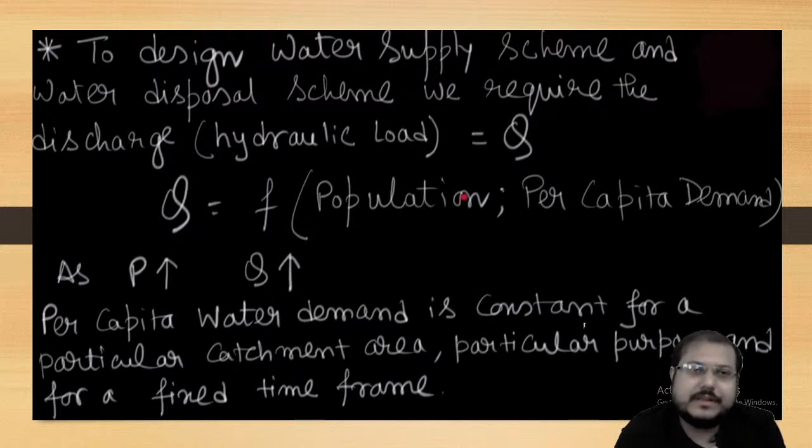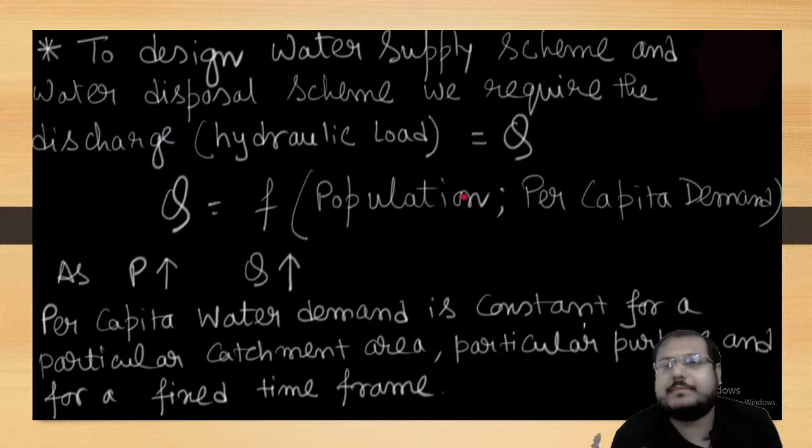So what will happen then? Then I will answer that person that, okay, you need to supply around 41 liters of water for this classroom for drinking purpose. How am I getting that 41 value? I'm just multiplying the population with the per capita demand. Per capita demand means, capita means person, demand.